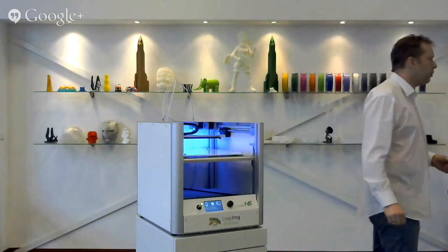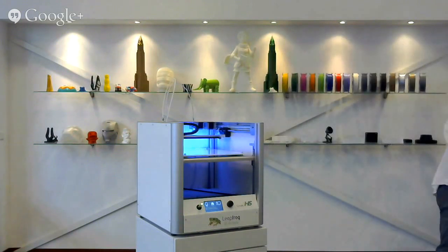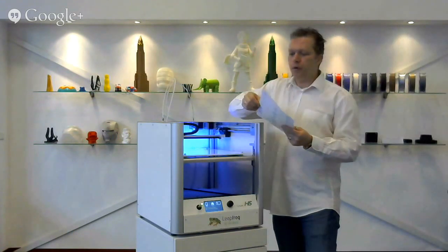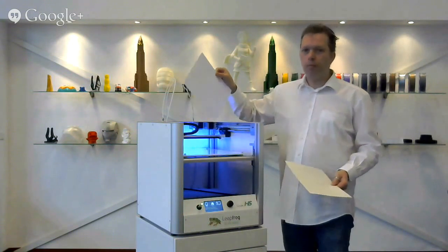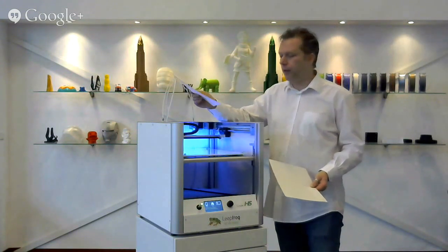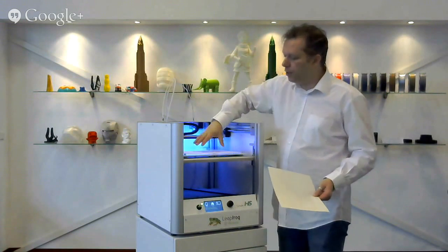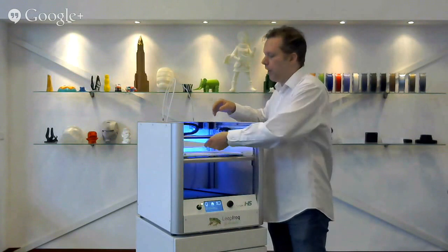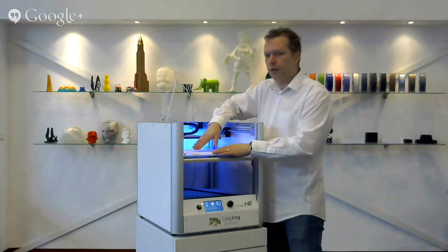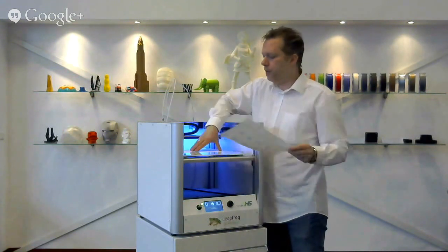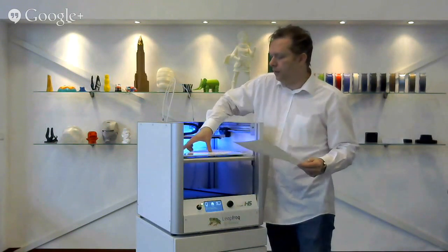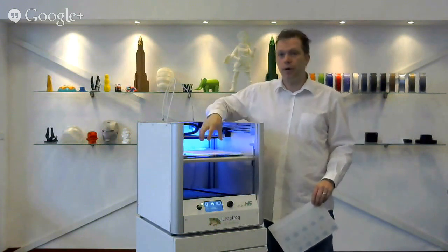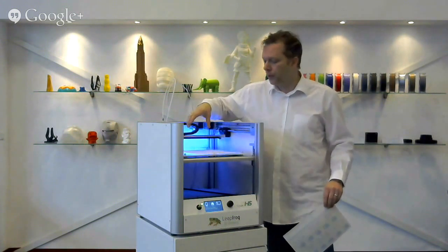After this, I want to show you how to place a sticker. From Leapfrog, we have these amazing stickers. They work perfectly for sticking your print to the bed. Before placing your print sticker, make sure that you know where you're going to place it. If you're going to make a large print, you want to have 2 stickers behind each other. If you're going to make smaller prints, it's easier to just have 1 single sticker in the center of your bed, and make sure in the software that your model is on the sticker and not next to it.